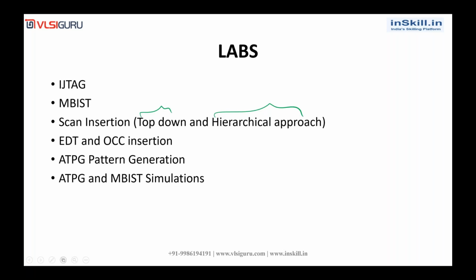And simulations, we will be covering only the no timing simulation, because in order to do timing simulation, we require a file called the SDF file, standard delay format. One file is required in order to do the timing simulation. That file is not available in our institute. So that is why we will be doing only the no timing simulations.